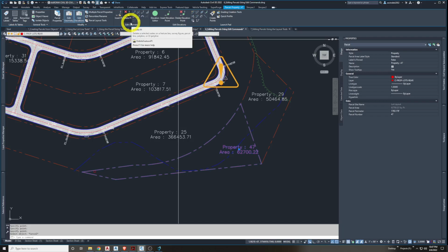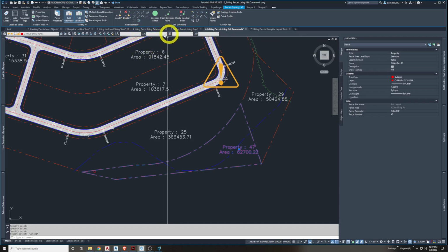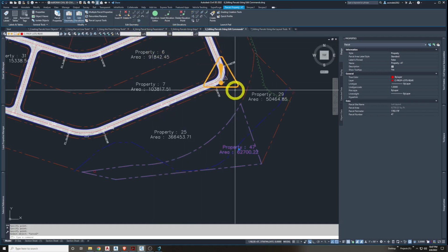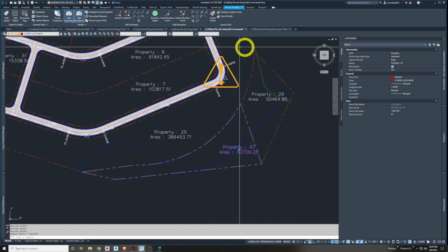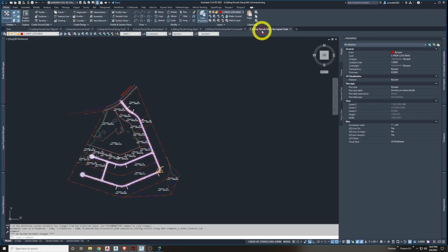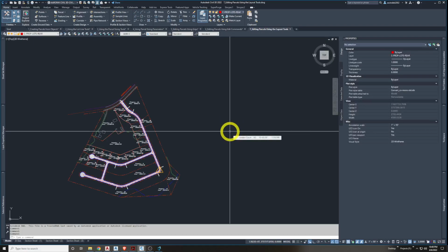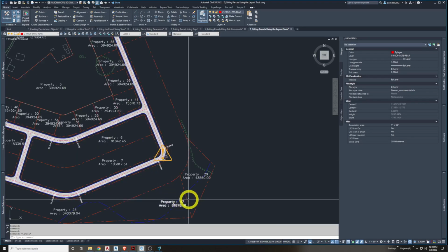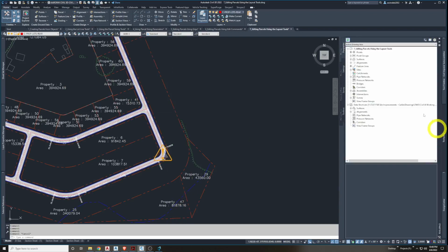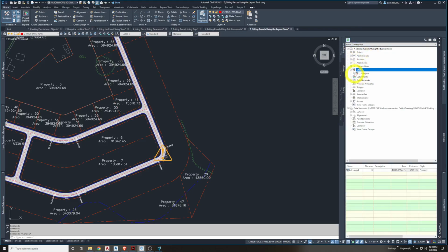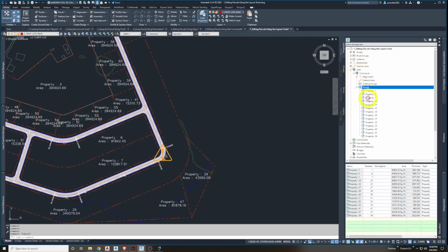Instead of creating brand new ones, we can slide and rotate them to meet new requirements. So let's go into the final area of this chapter, editing parcels using the layout tools. We'll start by going to property 28. And like I said, if you're having trouble finding it because we have so many, turn it on to master view first and go to your parcels out here.